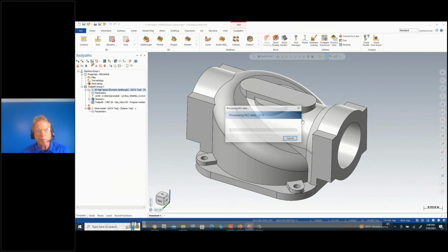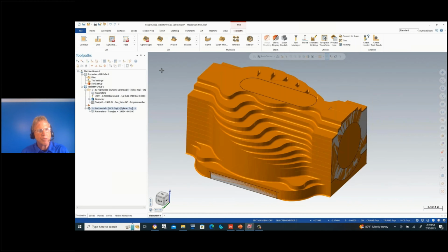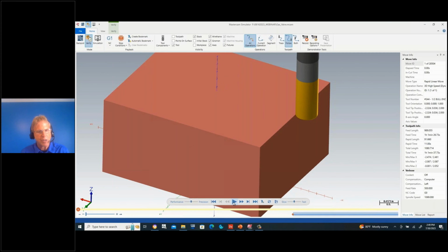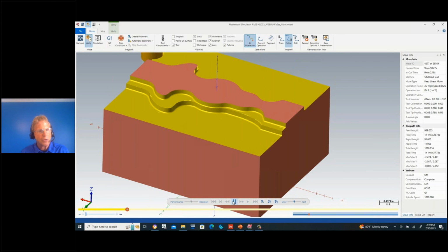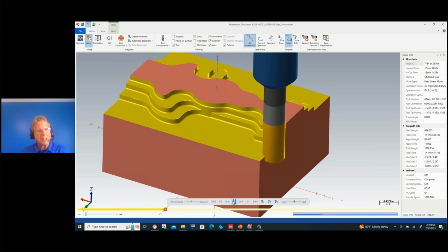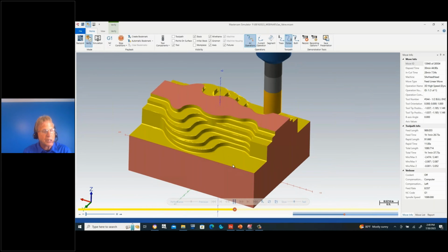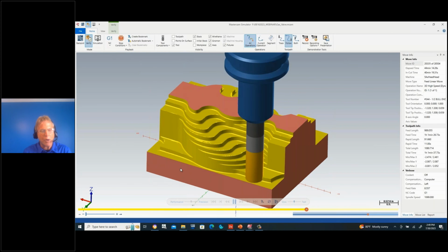Then in the Mastercam user interface, we can go through the processing of the toolpath. So again, we generate the OptiRough toolpath. Rather than showing this as just a back plot, we're going to go into the solid simulation tools in Mastercam and show it as a solid simulated feature. So this toolpath could end up being either a 2-axis or a 3-axis cut, but primarily it's two-dimensional. So it's a roughing toolpath to just rough away materials.